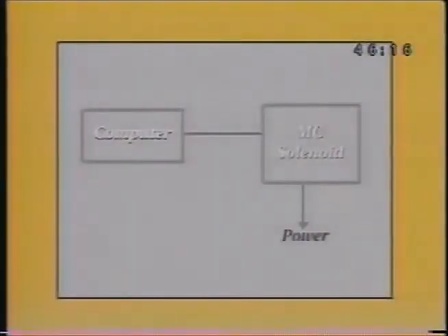By this time, you should be familiar with variable duty cycle signals and measuring their on time using Scopemeter's cursors. Now you'll learn how to use Scopemeter to display and measure the pulse width of a carburetor mixture control solenoid. Connect the channel A probe to the computer side of the MC solenoid. On most vehicles, that'll be the solenoid ground.